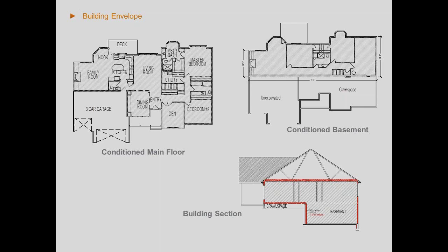The other thing is if you was to take that highlighter and highlight around the building thermal envelope on your plans and you have to lift up that highlighter, then you have a break in your continuous air barrier. The most recent codes require a continuous air barrier. You do not want to have a break in your air barrier. So another nice little helpful hint there.